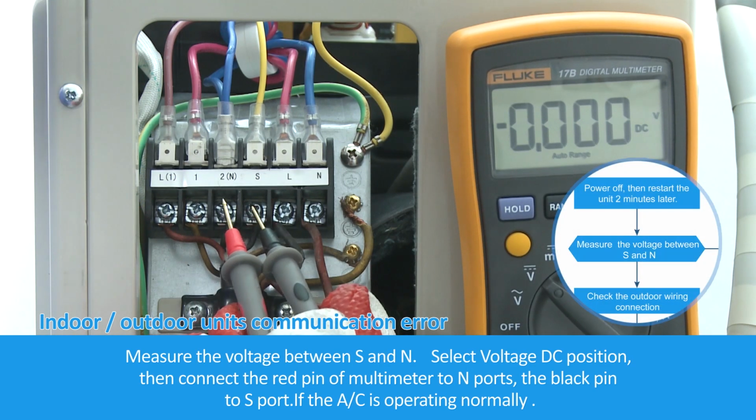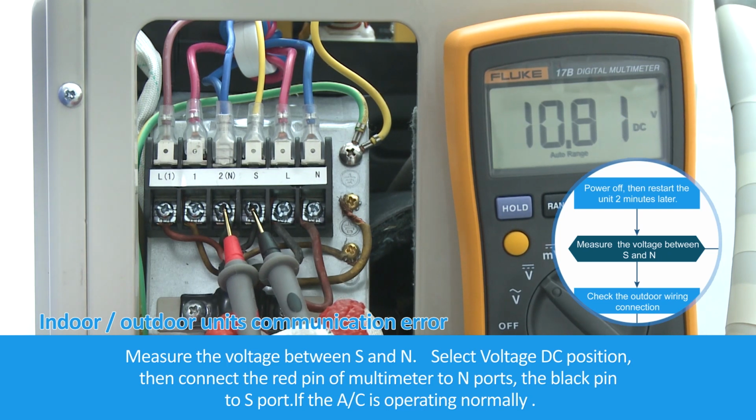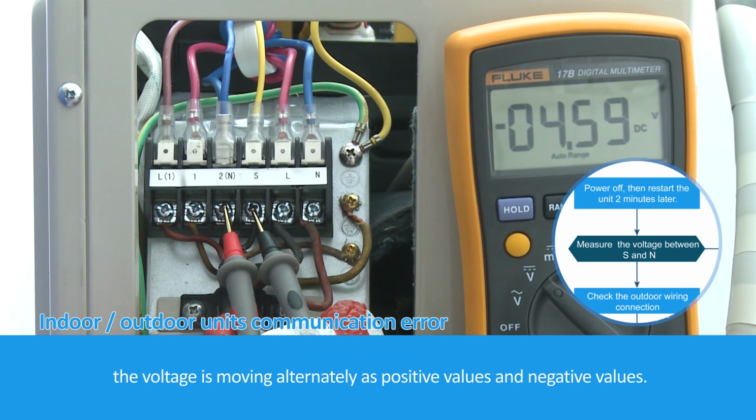Measure the voltage between S and N. Select voltage DC position, then connect the red pin of multimeter to N ports, the black pin to S port. If the air conditioner is operating normally, the voltage is moving alternately as positive values and negative values.